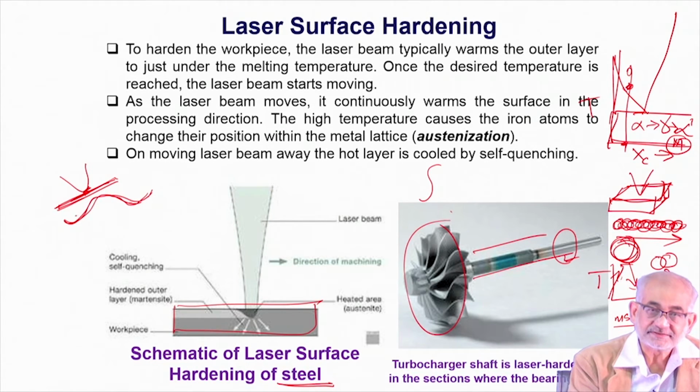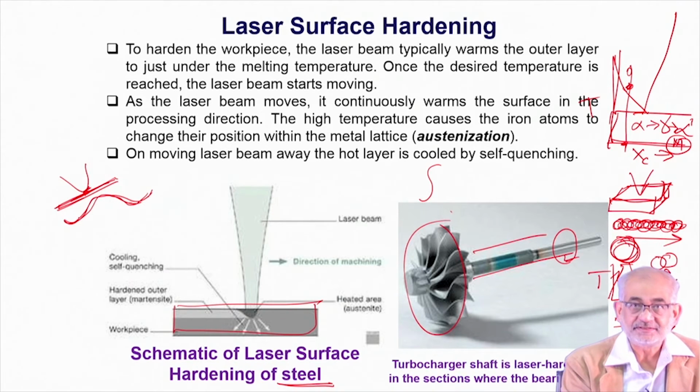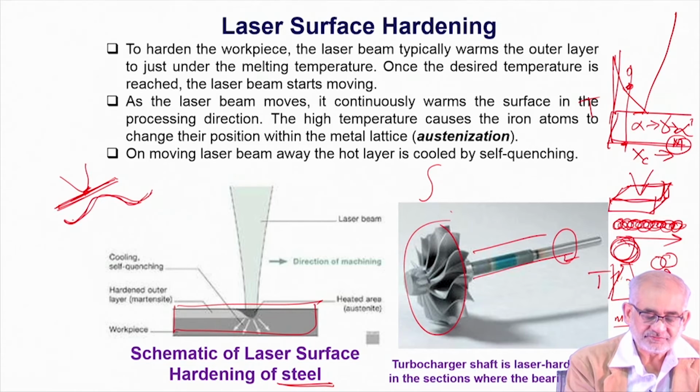Using that CAD-trained beam delivery system, even if the contour or shape changes, I can make the beam move up and down to ensure that the focus point remains at exactly the same position with respect to the surface.